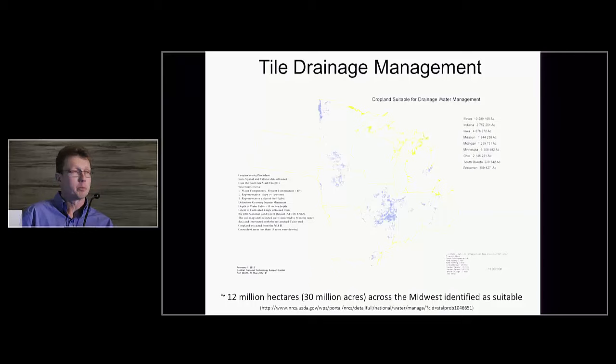It's a process that's targeting surface water quality and specifically nitrogen in surface water. And the thought is by controlling tile drainage or reducing the amount of tile drain discharge, you're reducing the amount of nitrate movement off of the fields and into the surface water. And it's kind of a one-to-one ratio. If you can reduce your discharge, you can also reduce nitrogen loads to the surface water.